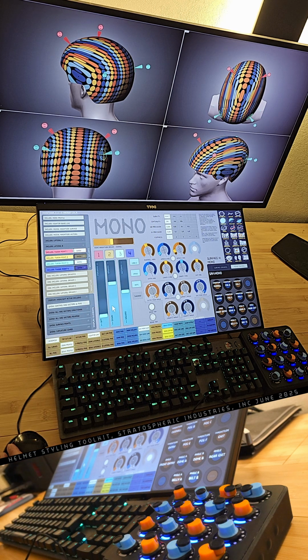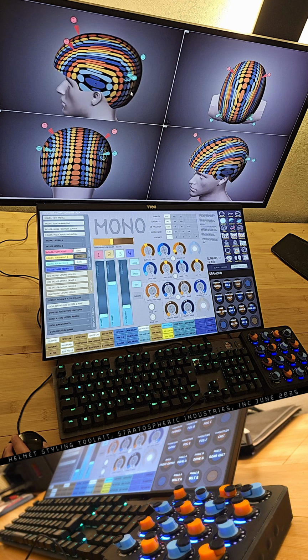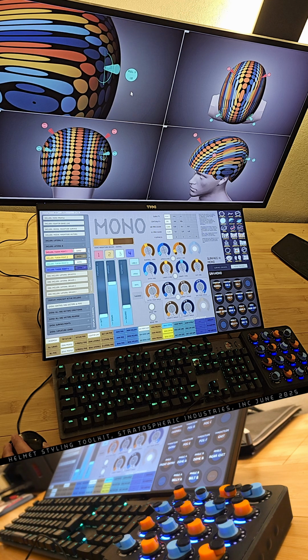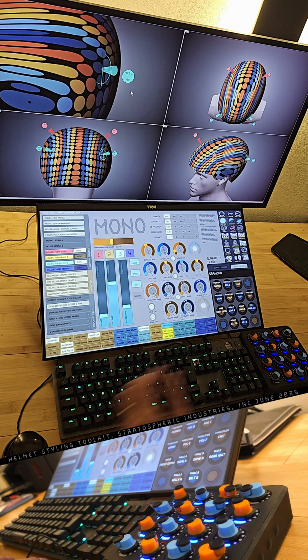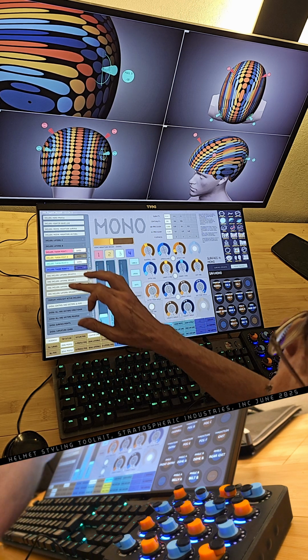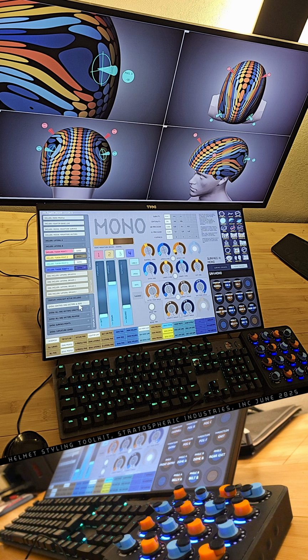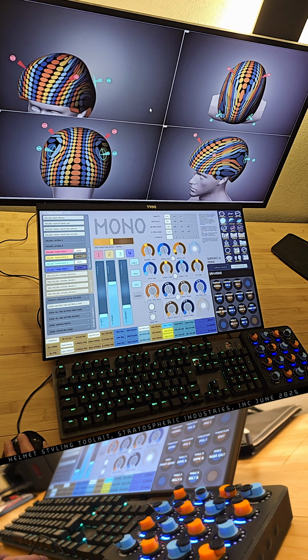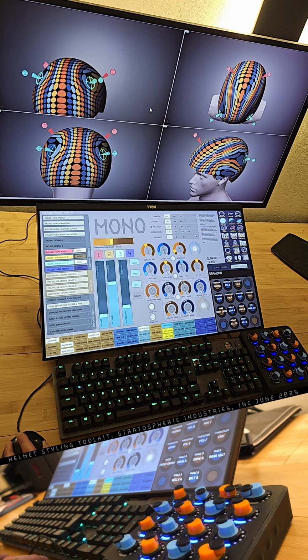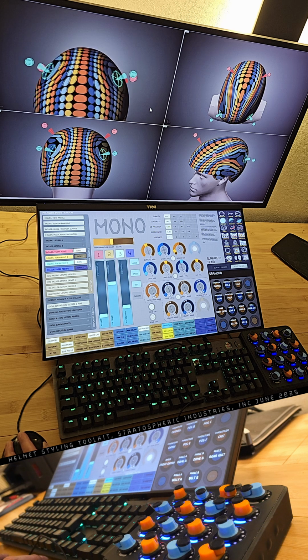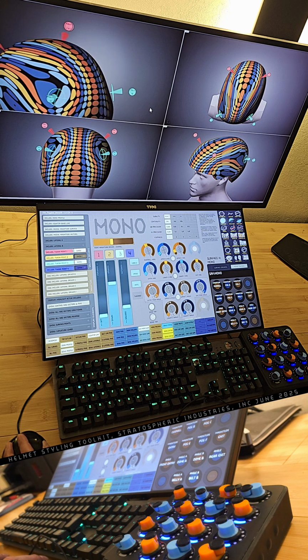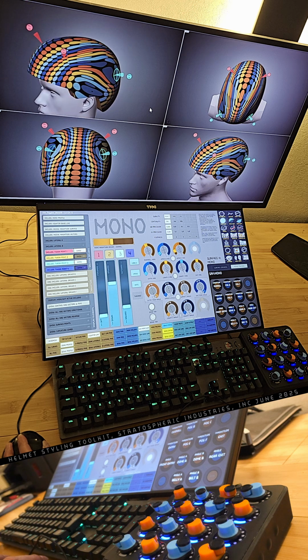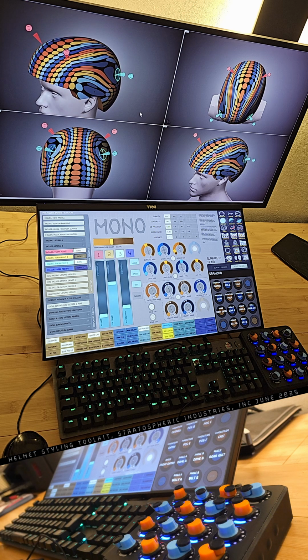I'm going to push that point inward. So I'm going to go from the middle line down. That pushes into the helmet, indicating minus 10 millimeters. And now we're going to include that into the solution here. All right, that's quite a dent in the back now. But you can see for the sake of illustration the effect that has on the design. It pushes in rearward on the helmet. And this whole surface is then quite smoothly blended.